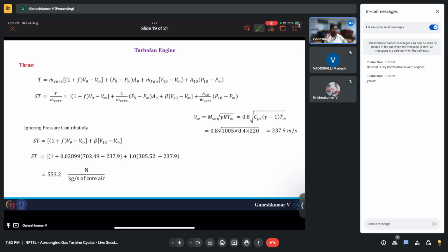Additional things that we took into account, the difference in solving a problem from turbojet to turbofan, is we have an additional fan component. We have to apply some equations to find the station pressures and temperatures across the fan, and we need to take care of energy balances in the combustion chamber. Combustion chamber, anyway, we usually do. The change is in the turbine energy balance, because the turbine here also needs to drive the fan. Okay, so that is the difference.